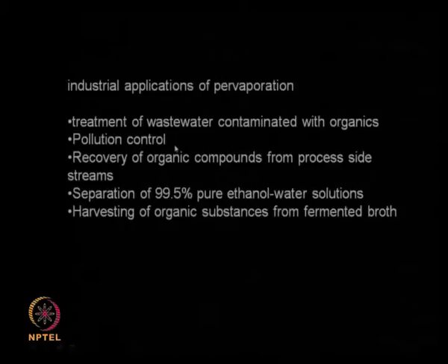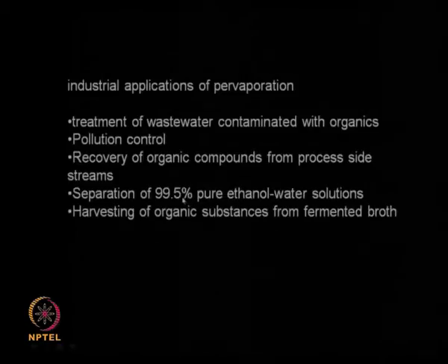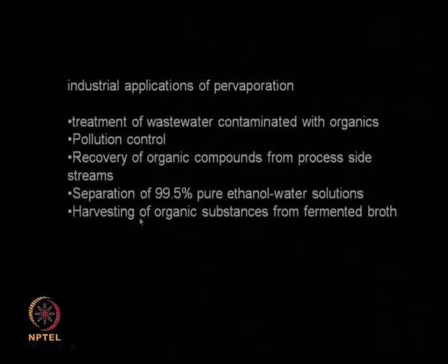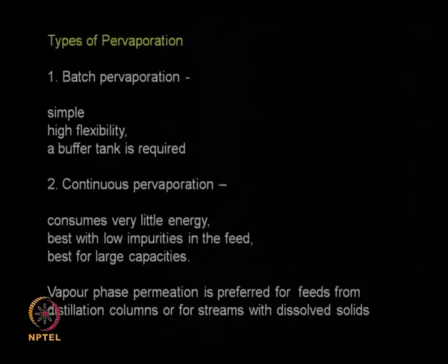So pollution control, recovery of organic compounds from process side streams. Sometimes I am doing a reaction, there could be an organic contamination, so I just want to remove that so that I can recycle the process stream. Separation, purification of 99.5% pure ethanol from ethanol water systems. Harvesting of organic substances from fermentation broth. So quite a lot of applications of pervaporation are coming into the market.